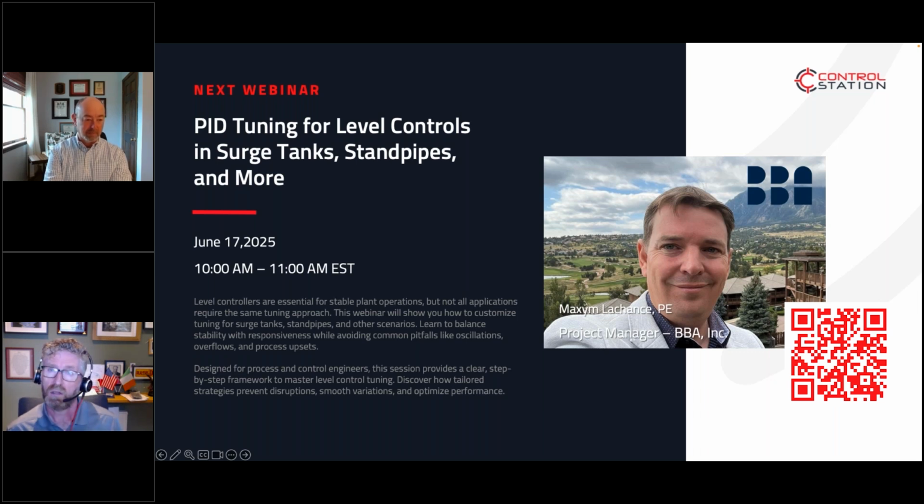First of all, vendors have provided very expensive, very capable valves and pieces of equipment that have warranties, guarantees and reliability built into them. They've done a lot to do that, and we have to be respectful of that. A vendor says it has 1 million cycles on the valve. That sounds like a lot, but if you're constantly oscillating that valve because you've tuned the process overly aggressively, or you're constantly letting the packing dry out because of the environment you're operating in, you're making it hard for the valve to be successful, I suppose.